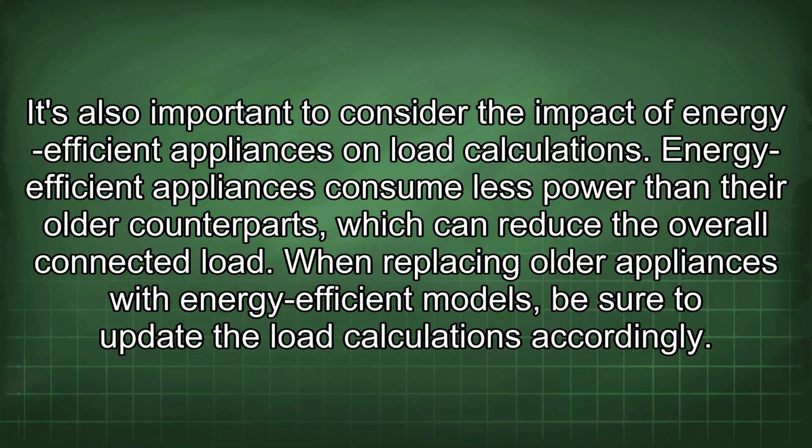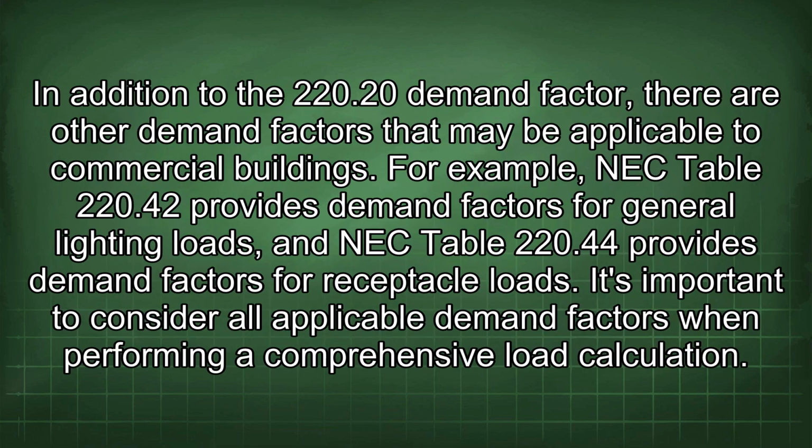It's also important to consider the impact of energy-efficient appliances on load calculations. Energy-efficient appliances consume less power than their older counterparts, which can reduce the overall connected load. When replacing older appliances with energy-efficient models, be sure to update the load calculations accordingly. In addition to the 220.20 demand factor, there are other demand factors that may be applicable to commercial buildings.